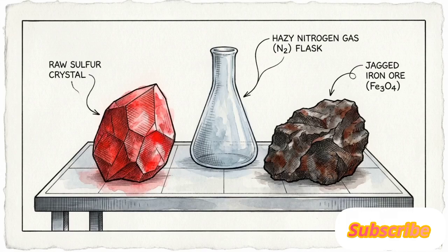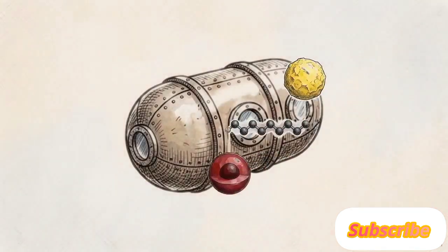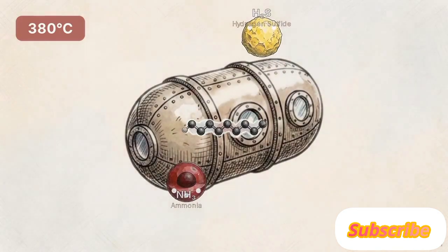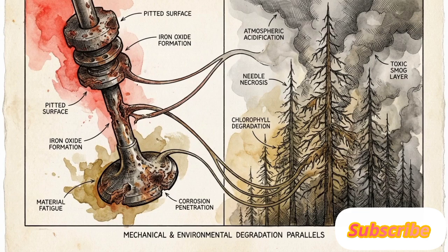Raw crude typically carries sulfur, nitrogen, and iron that must be removed before the product is finished. In hydrotreating, chains enter a 380 degrees Celsius reactor with sulfur and nitrogen atoms attached. Pure hydrogen is pumped in, aggressively severing the contaminant's bonds. Nitrogen converts to ammonia, and sulfur to hydrogen sulfide gas. Both are removed, leaving a pure, stabilized paraffin chain. Without this chemical wash, these fuels would carry corrosive impurities that damage engine components and release sulfur into the atmosphere as acid rain.